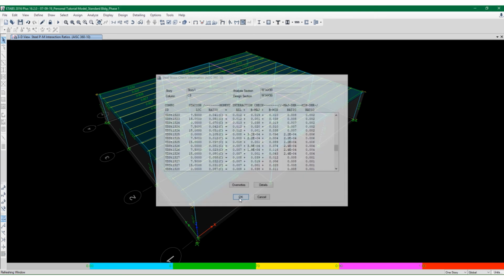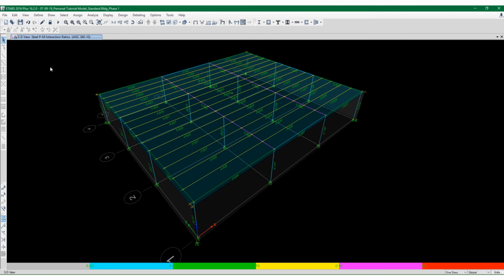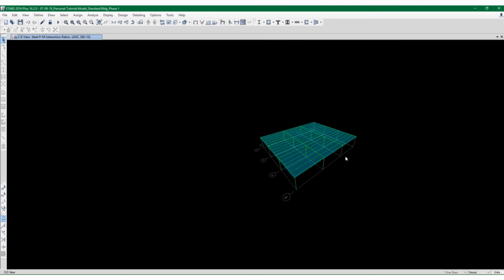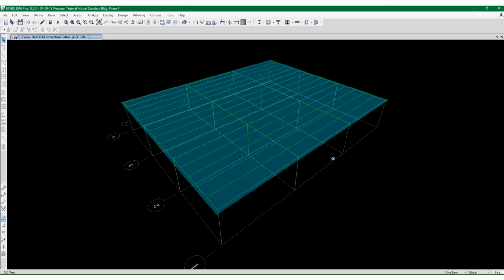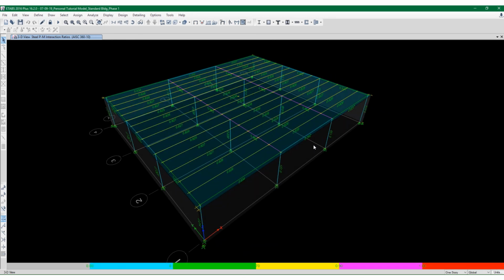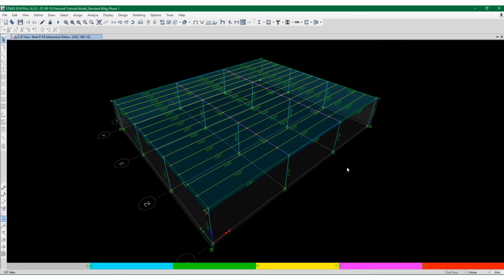All right, so with that, we'll conclude this video and our comparison of ETABS results with RAM results using, well, I guess, a modified P delta analysis that allows us to combine the linear elastic load cases algebraically instead of having to run P delta analysis on load combinations directly, as is required when you use the iterative method and so-called rigorous second order elastic analysis. All right, well, that's it.